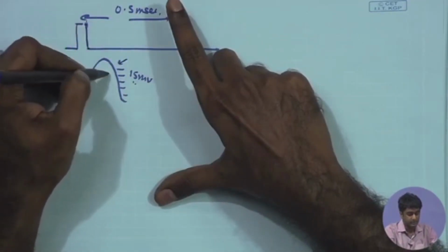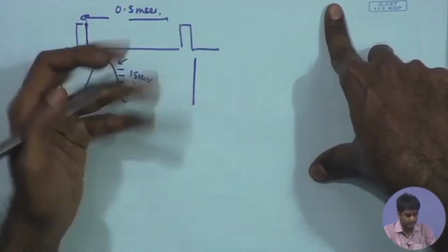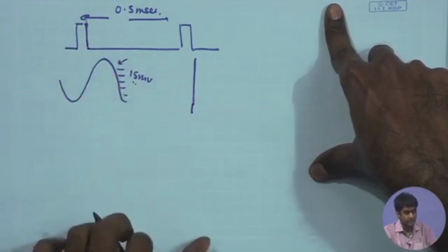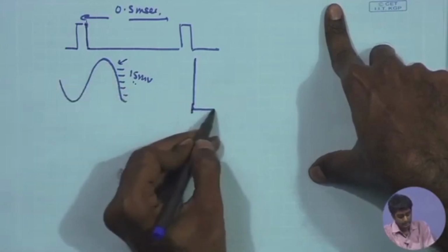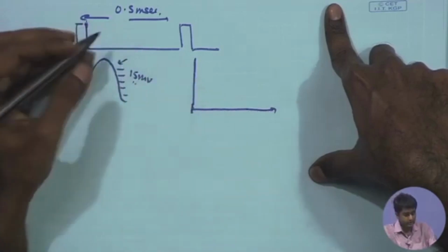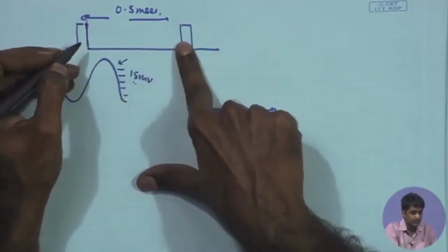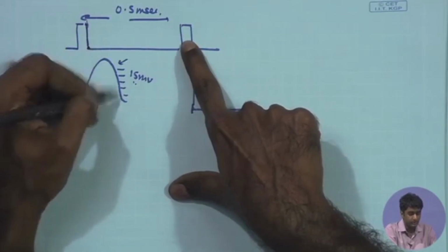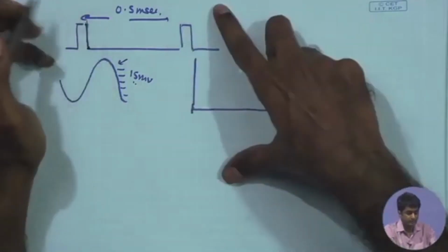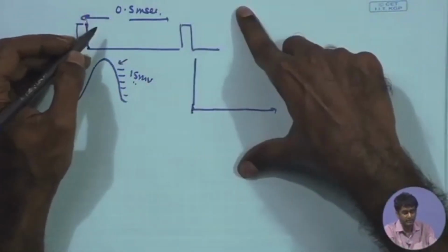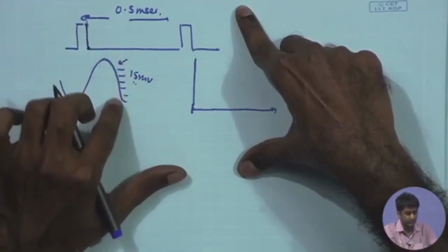Now if I look at the first metric, that is the gain of the comparator, we can arrive at the gain in several different ways. If I look at the analogy for the ramping circuit that we are looking at, the voltage is going to increase at different time steps continuously. How many time steps do we want in this interval, so that the number of quantization levels here equals the number of quantization levels we want in the ADC? We know that the ADC quantization we have chosen is, say, 7-bit, and therefore we are looking for 127 different levels, and so the overall voltage signal is divided into 127 different segments.